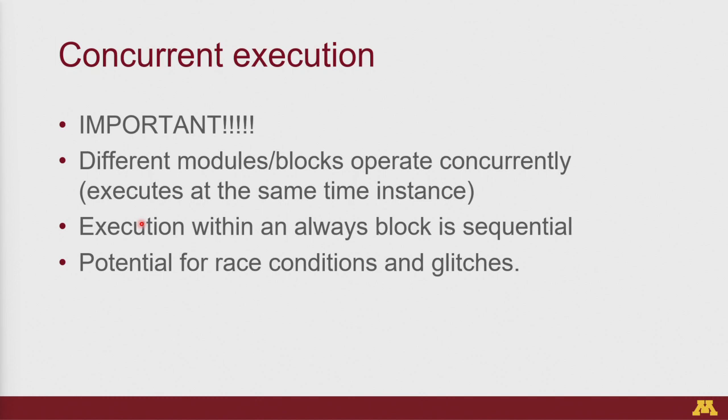The way you think of it is that an always block is just a block of code where you can write more complicated logic so that you don't have to break it down into the bare metal code like your behavioral code. So within that it will be sequential, but you can define multiple always blocks, and those different always blocks will be parallel to each other. Yeah, and the best debug hint I can give you is that if your code depends on the sequential nature of it, most likely it will break when you design it in Verilog.